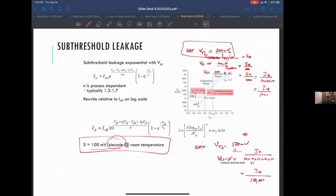Okay, so basically it's saying I can reduce my subthreshold leakage current significantly by just making my threshold voltages higher, if everything else was equal. Here's the device with everything the same, a 500 millivolt threshold voltage versus a 300 millivolt threshold voltage. Do you guys follow me there?